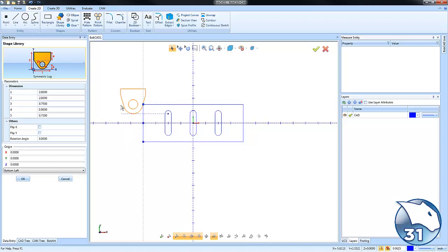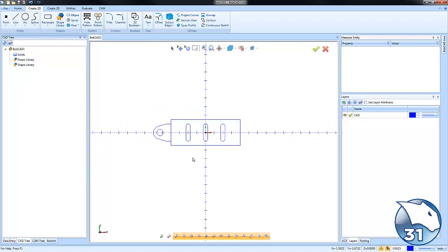So what am I going to do here? Well, one of the things that I'm going to do is I'm just going to rotate this minus 90 degrees so we can get one lined up for this edge. And then I'll also adjust its reference location and make it easier to line up the part. I'll choose this mid position here, and then we'll choose OK. And you'll see that we were able to add this lug on this side of the part.